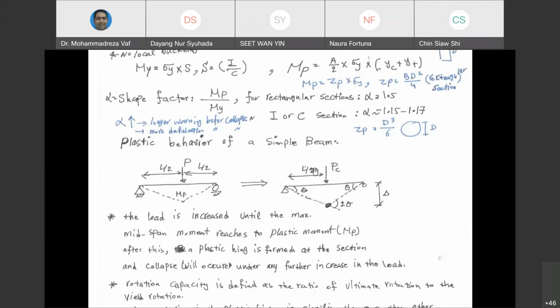So when the load is increasing, the bending moment is going to increase until it reaches the plastic moment. We said more than the plastic moment is not possible, because that is the time that the structure is going to fail. And if you remember in the video, we said that for a simply supported beam, in order to fail, we need to have 3 hinges in one span. Since in this beam, 2 supports are already working like hinges because the bending moment over there is 0, the moment that we get another hinge, which comes from the plastic condition inside the beam, it is going to reach its failure condition. We also always assume that at the time of collapse, the deflected shape follows a linear condition, meaning we don't assume that there is bending inside our segments.